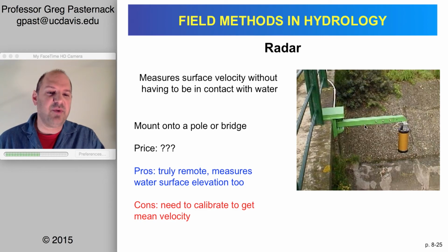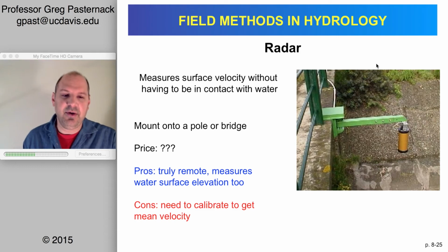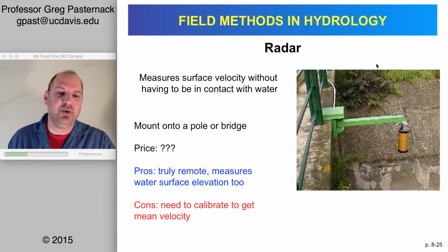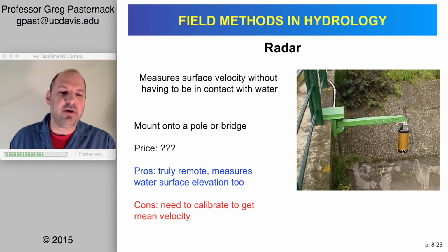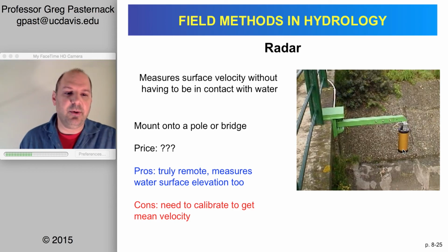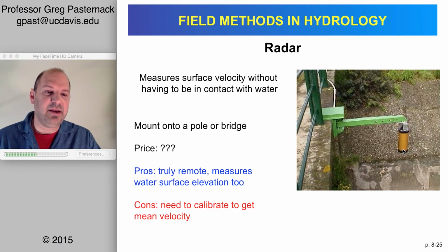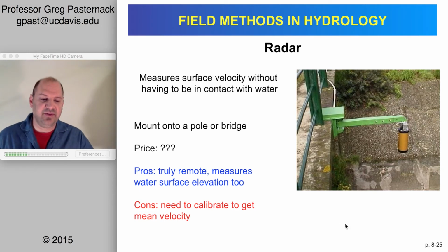But again, there's always a range resolution trade-off. So if you put this on a super tall pole, then you're safe, but you won't have the same resolution and range that you would get if you put it closer. So you have to figure that out. These are just relatively expensive, glorified float kind of technology. Of course, they can be data logging, which is really valuable, and they're not going to get hurt by sediment transport and stuff in the flood or woody debris, let's say. It's just you're only getting the surface velocity, so you need to calibrate that somehow to get to mean velocity.